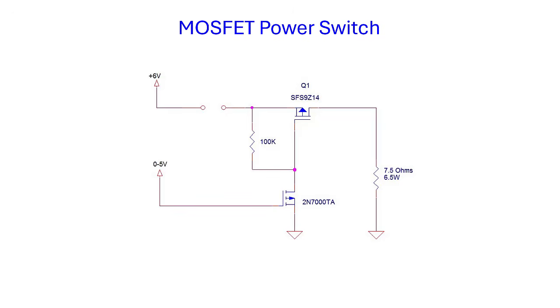And by the way, the 7.5 ohm load resistor will get quite warm once you power your circuit, so you do not want to leave this circuit powered for an extended period of time. Please be sure and return the resistor to the lab monitors when you're finished.